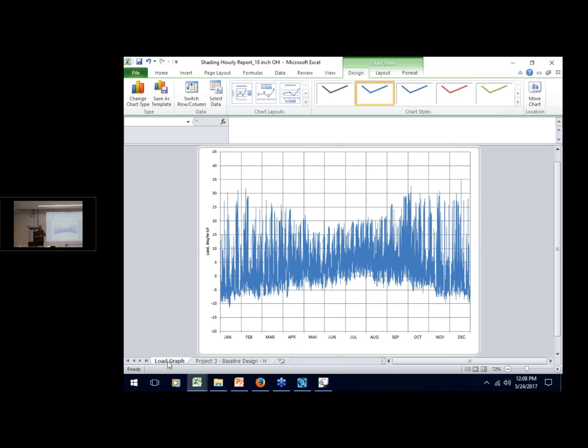Now, you may want to develop some QC checks for typical simulation problems, like when we're doing a VAV system, we do these five variables. But like we were talking about, shading might be really important on one project and not even an issue on the next project. So you've got to take your cue from what I'm always asking myself: what design questions can I answer for the design team using this tool?